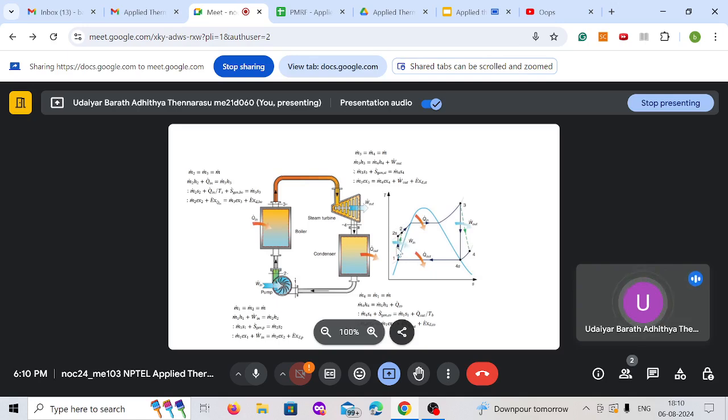So this makes larger sense because the work done on any fluid is minus V dP. So here the specific volume of your liquid is very small compared to any gas. So in that case, the work done for your pumping or process of compression is very small for a liquid compared to a gas.